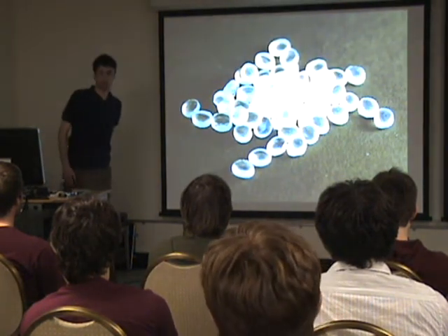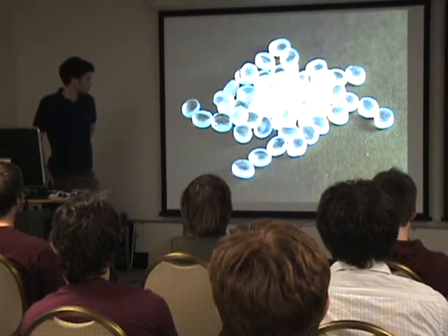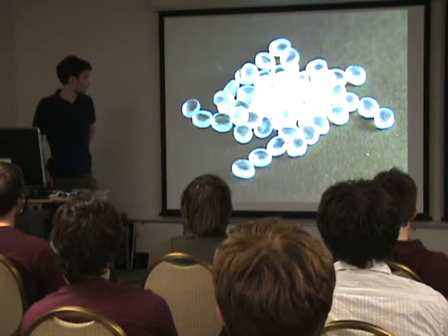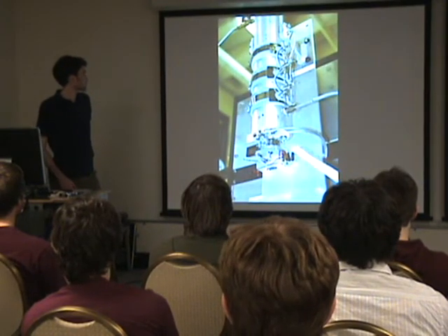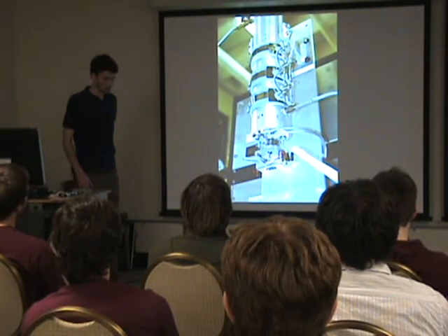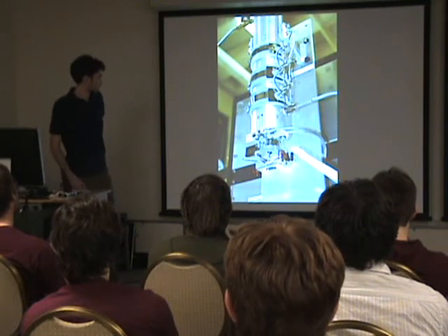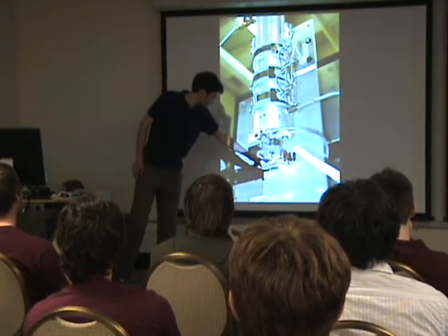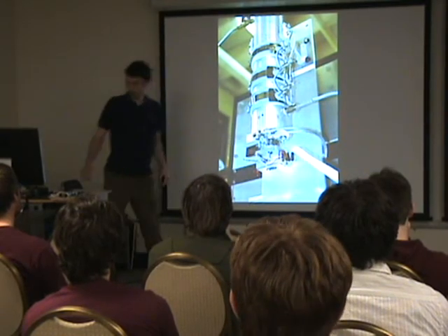Here's our pellets that we have inside. Standard, it's more or less hot glue, run-of-the-mill plastic. And then here's another image of our extruder. So you can see if we get that cutaway, our extrudate surface is no longer in contact with our die as we're exiting our die head.